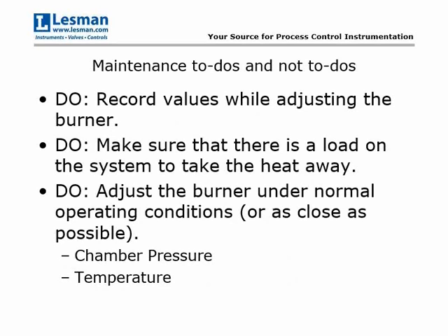There was an application that I got into at one point in time where we didn't have the heat load, and even though you're below the temperature set point of the high temperature limit, the environment that the burner was firing into was a lot more dry because there was no product in there, and it caused a small grease fire at one of the recirculating fans.